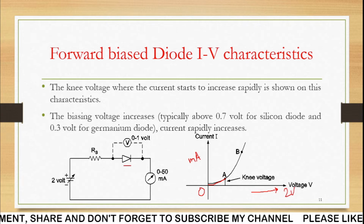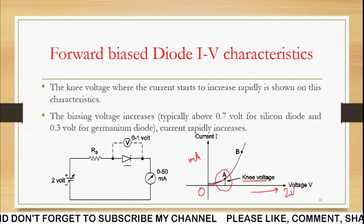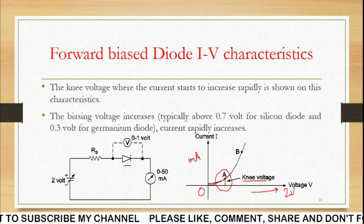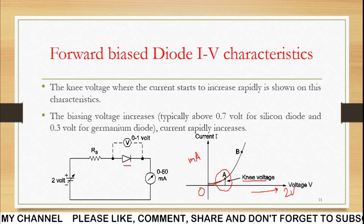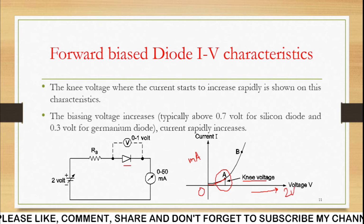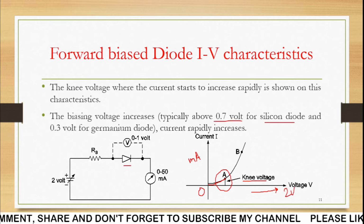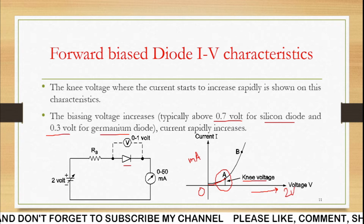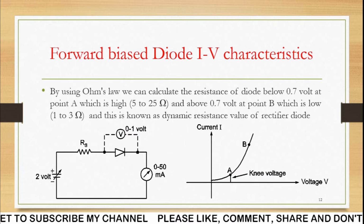So you can see the current increases at a point called the knee voltage. This is the term available in the forward bias characteristic of a diode. Knee voltage is the point where the current starts to increase rapidly, and that is shown in this diagram. As the biasing voltage increases, typically for a silicon diode it is 0.7 volt, and for a germanium diode it is 0.3 volt. So after that knee voltage the current is rapidly increasing.